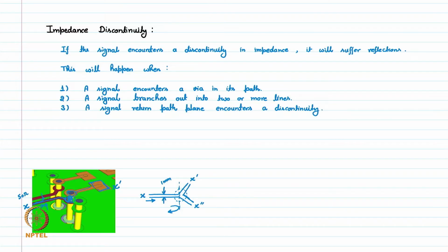In this case, we have some return path for the signal, and if there is a discontinuity or a split in that return path, that also causes impedance discontinuity.